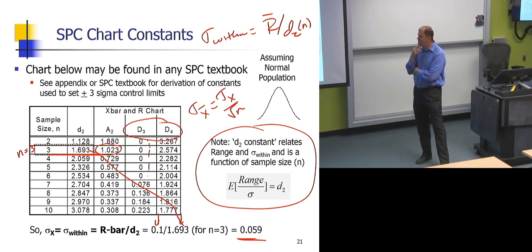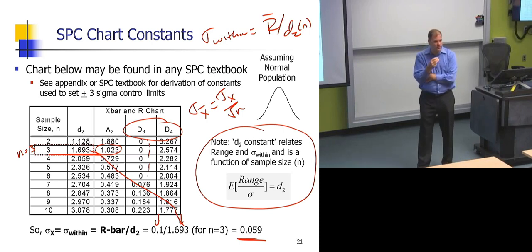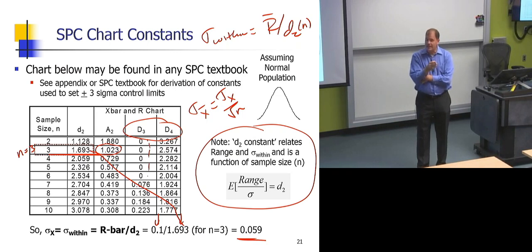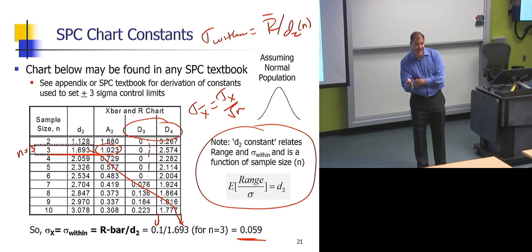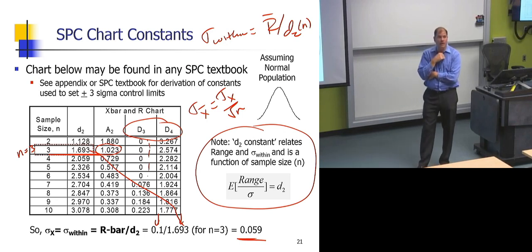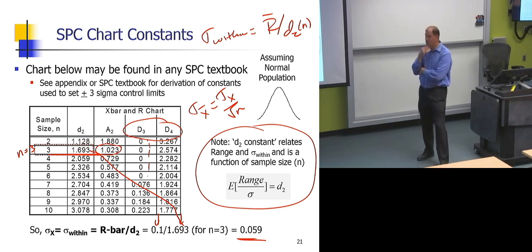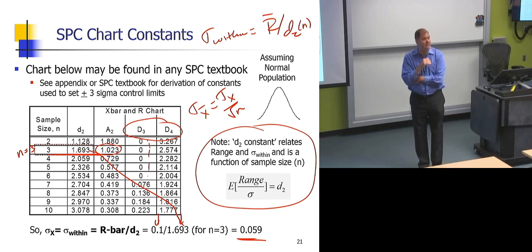Let's say you measured 10 times. You measured 10 different units, and you got continuous data now, exact same value 10 times in a row. We would actually assume that that's not likely to happen, and you'll end up getting a below the lower control limit, because your value is going to be 0. Probably a measurement error, probably an assignable cause.